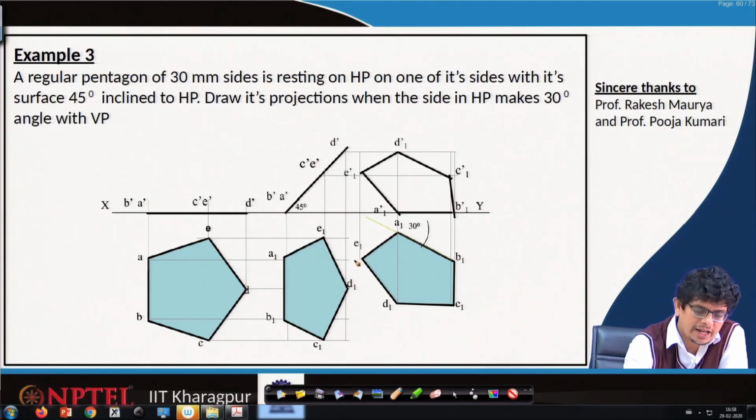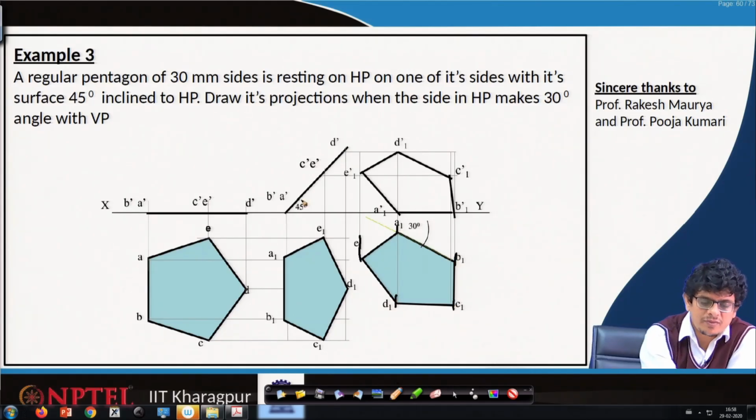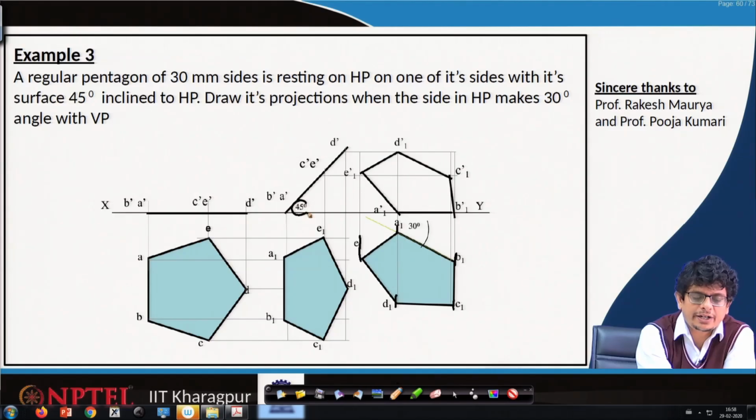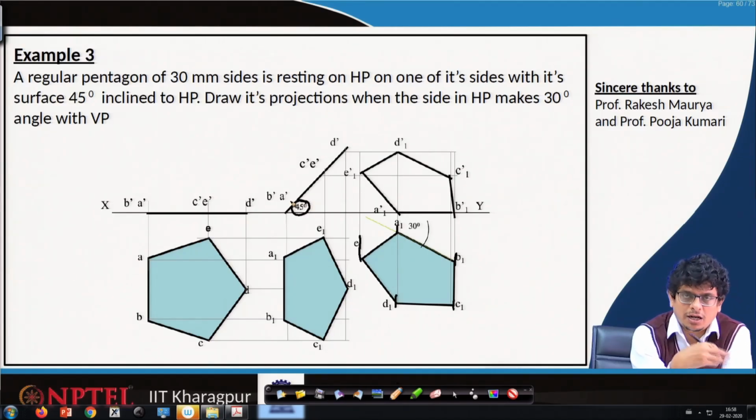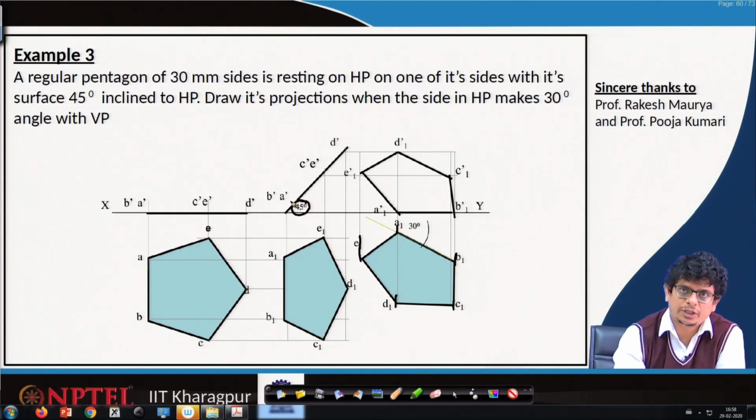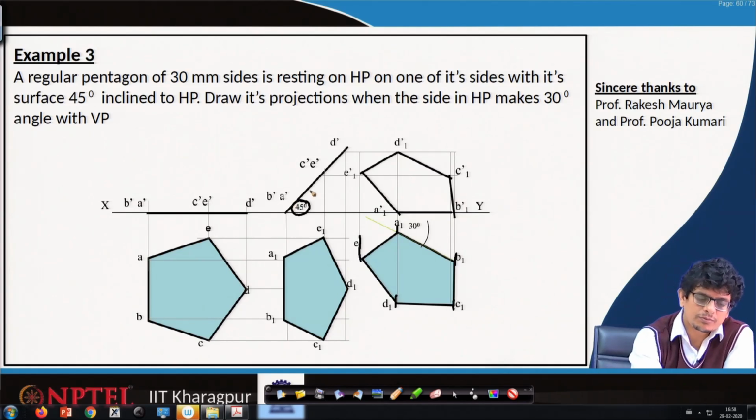Once that is done, again project these lines from E, C, A, B and C, and already we have rotated into 45 degrees in the vertical plane. So, with the horizontal plane, the angle whatever it is making, we observe the locus points where A intersects with A prime, called A1 prime.